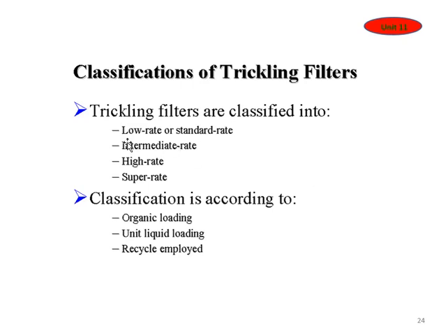Trickling filters are classified into low rate or intermediate rate, high rate, and super rate, based on the Q. If it is treating a high Q, it is super rate. If it is treating a very low Q, that is, flow rate, then it's a low rate. So according to the Q, we can classify.